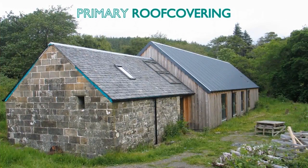It's not only traditional slating that will affect condensation in lofts. Even using a standard tiled roof, the air openness of the outer cover must be accounted for, and if the tiles are particularly airtight or if a metal roof covering is specified, additional venting of the batten cavity may be needed. BS 5250 and BS 5534, both of which we'll discuss shortly, outline when coverings can be considered air open, what measures must be taken if they're not, and what effect wind uplift will have both on the outer covering and the roof underlay.